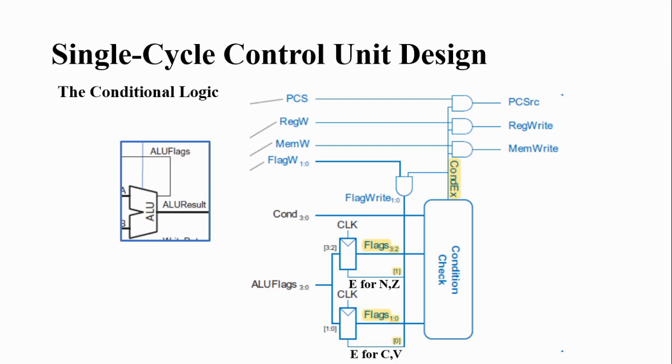But other microcontrollers are not like that. There are separate conditional instructions there. But here it is not that way. Only if a condition is satisfied will the corresponding instruction be executed. So all the instructions have a condition field.